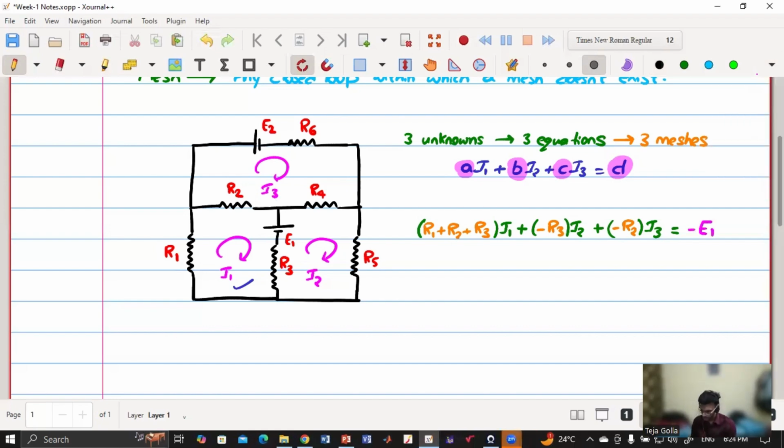Sir, here current goes from positive to negative, then the current direction is anti-clockwise. Yes. So basically, whatever conventions we consider, we will fix that the current is always flowing in the clockwise direction. When we solve the equations, we might get the current positive or negative. If the current is positive, it means our assumption that the current is flowing clockwise is correct. If the current is negative, it means the current is actually flowing counterclockwise. But we will not consider counterclockwise at the beginning.